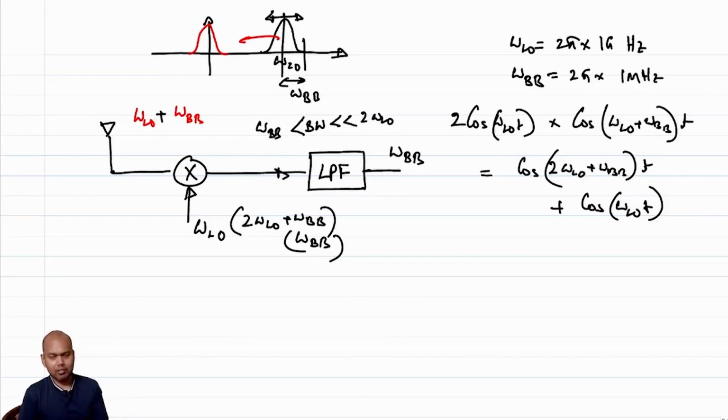if I take the GSM standards, then without getting into exact frequency bands, we know that your receiver band and the transmitter band are centered around 900 megahertz, and the frequency separation between the receiver band and the transmitter band is approximately 20 megahertz, right? Which essentially means that I am holding a cell phone, receiving something at say 910 megahertz, and somebody is transmitting sitting next to me at 930 megahertz.